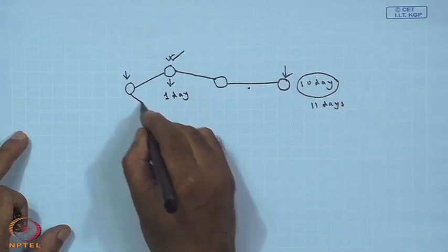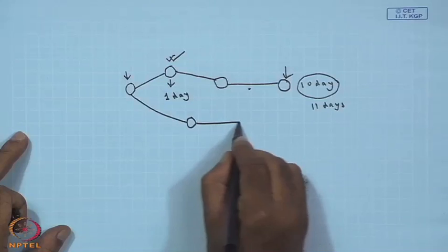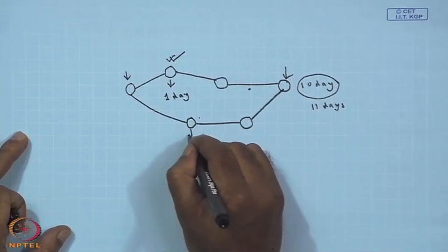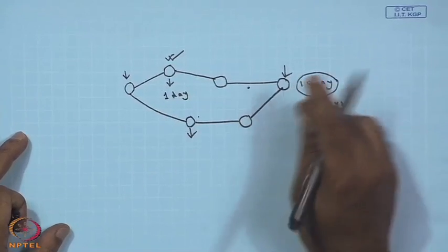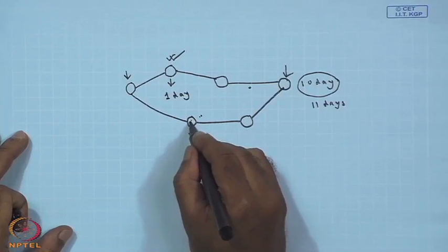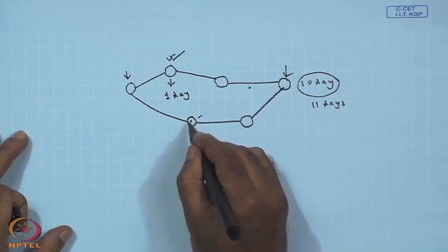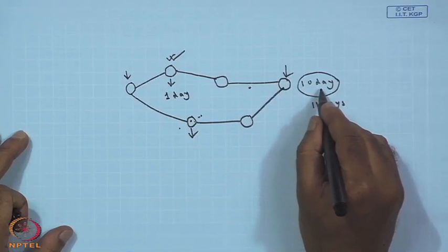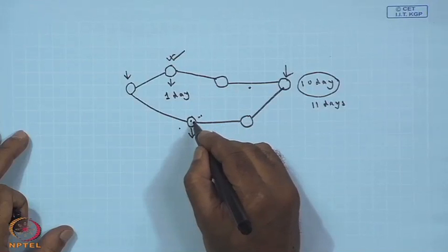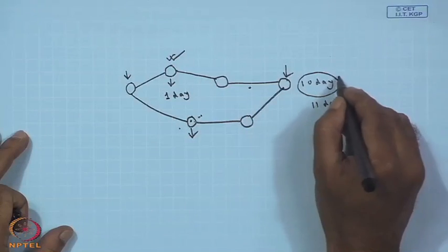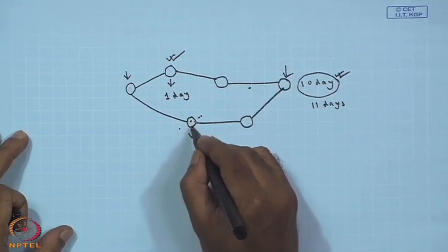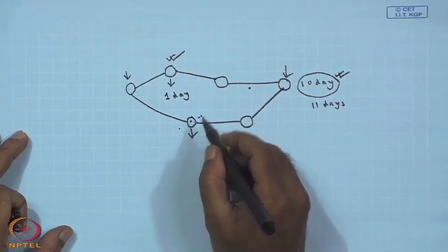If you see in the figure, suppose I have drawn something like this, along with this, again the end node. For this particular activity, this will be a non-critical activity. If I start it 1 day earlier or 1 day later, this will not affect the project completion time. Or in other words, if this activity starts beforehand or starts after 1 day, the project completion time remains 10 days only, then the activity is known as a non-critical activity. So, I hope it is clear.